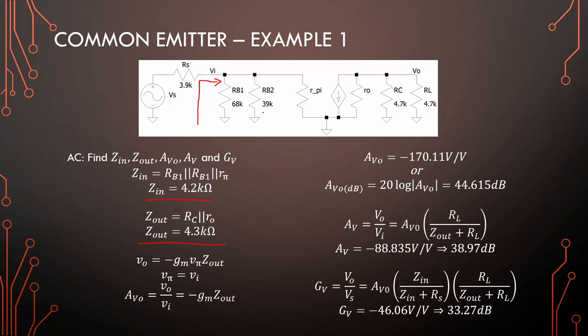Right. Now, I'm not going to do this with all the amplifier types, but to find the maximum gain, you need to find V out over V in. Okay, so this here is a current source, and its equation is GM times V pi, so it's voltage dependent from V pi sitting over R pi over there.